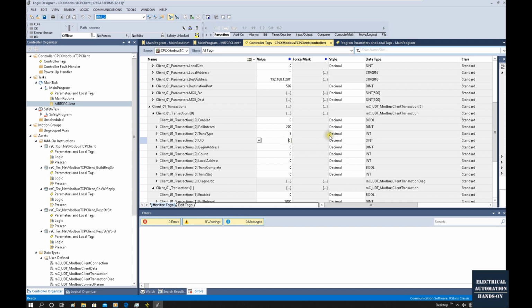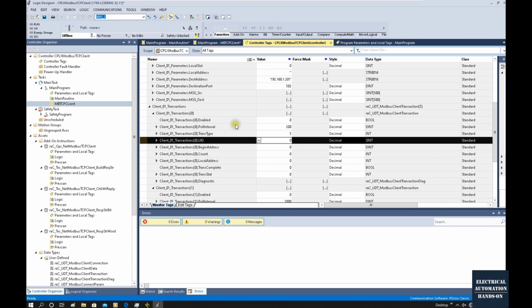You need to check the manual for this module and check the UID setting there. So by default, we will leave 0 here, but you need to take care about this. Sometimes every setting is correct, but you cannot get the Modbus TCP connection successfully. That's because of this. So you need to be careful about this.